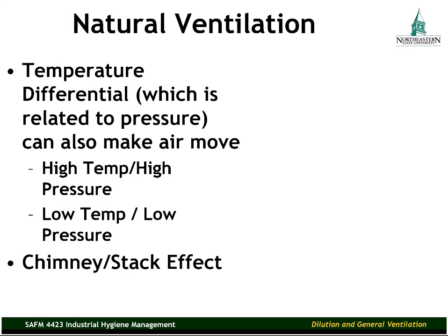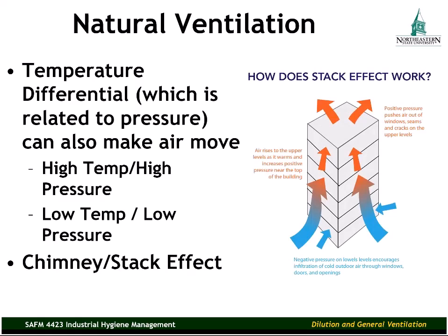Also, and this goes along with wind flow through a space, it also goes along with temperature differential, we have what we call a chimney effect or a stack effect within structures, where air enters a structure and it rises, and as it heats, it rises and will be dissipated outside the building. Just like fire gases coming up through a chimney in your fireplace at home or your wood stove at home.